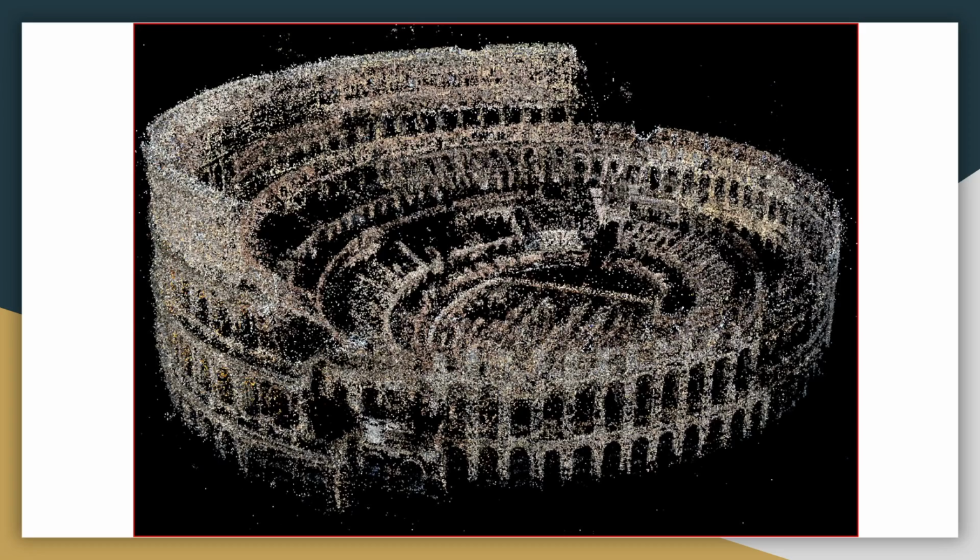So yeah, basically one more thing. I said that the stereo cameras will combine the images to give a disparity image, and from the disparity image you get the point cloud. So what exactly is a disparity image? A disparity image is a two-dimensional image where each and every point in the image has a transition from black to white. It can be completely black, or it can be gray, or completely white.